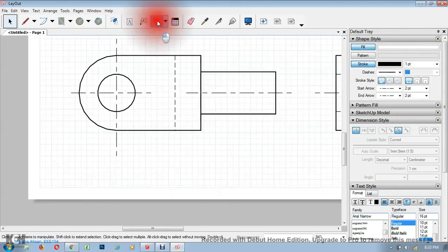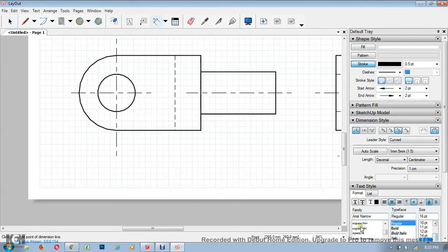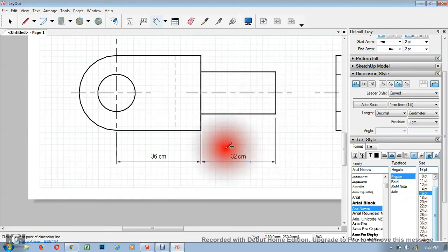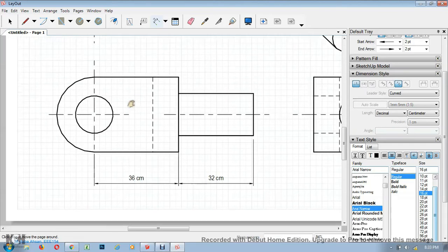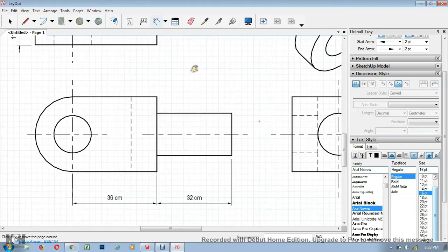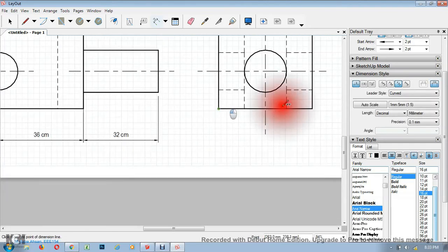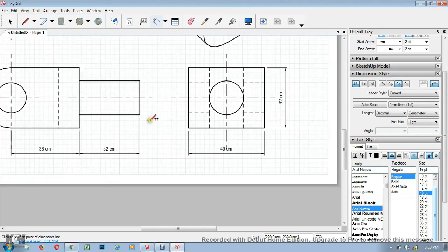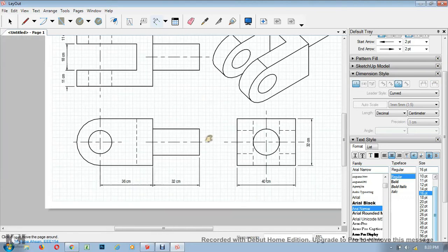For this one again, let's see if everything is okay. Yeah, everything looks okay. So I'll first put a dimension here, and this one as well as this one. But if I put a radius, I will not get it automatically. So let me finish giving dimensions here, and after I'm done putting linear dimensions, I'll go for the circular ones, meaning putting dimensions on center.